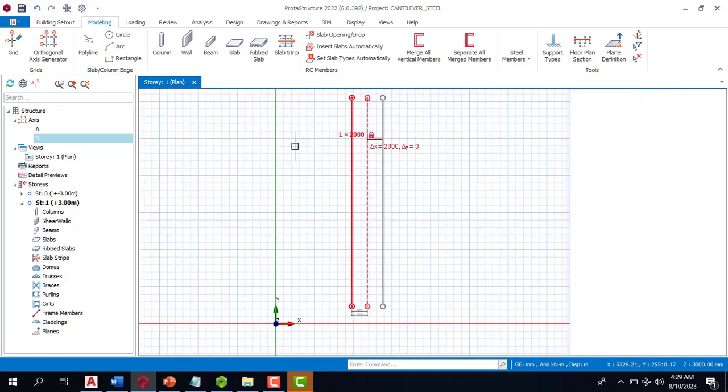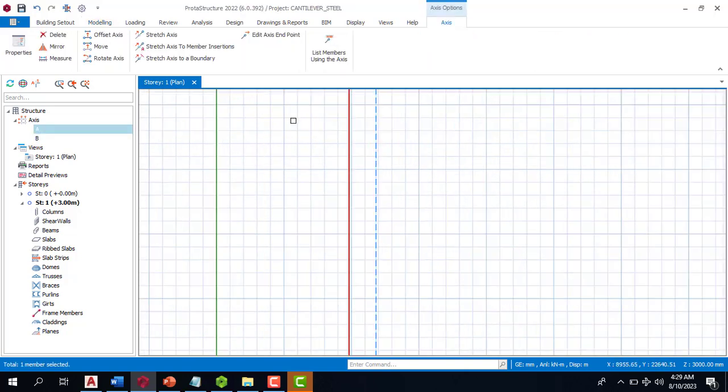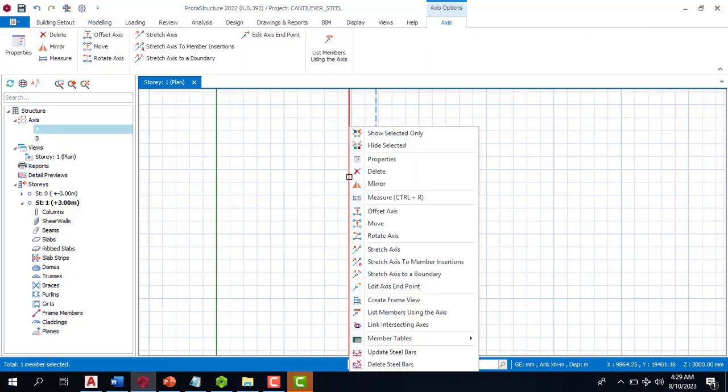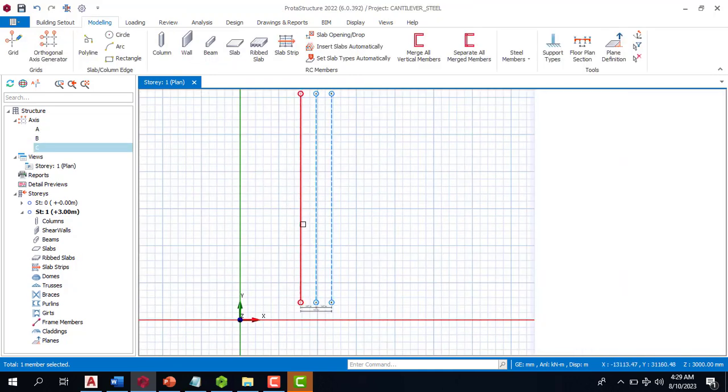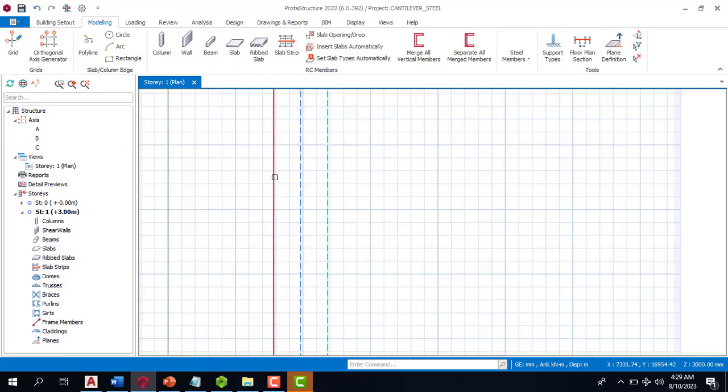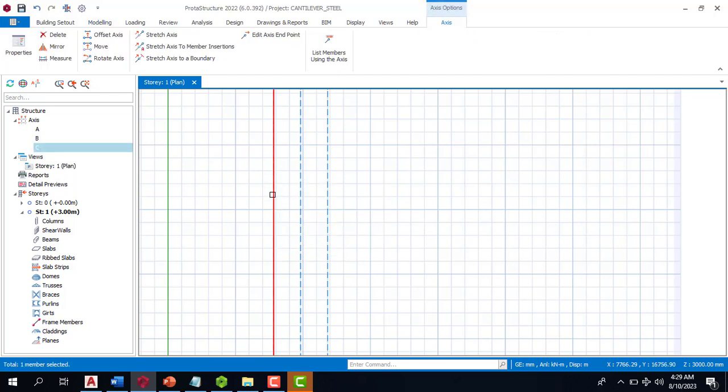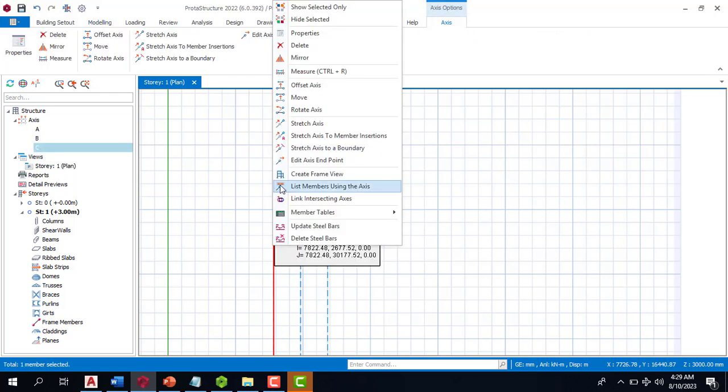But if I am going in the opposite direction, like backward, let's say I want to go this way, I will type F2, and I will have to type in the minus before typing in the distance. You can see it has gone backward, but I don't have need for this. I'm going to delete it.